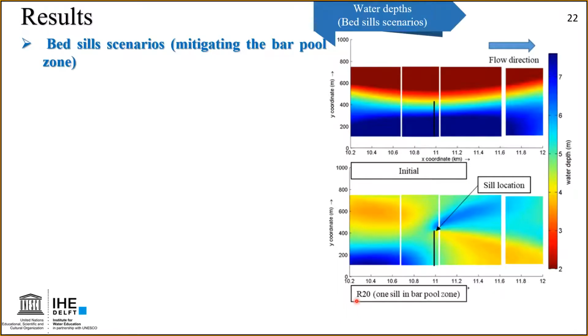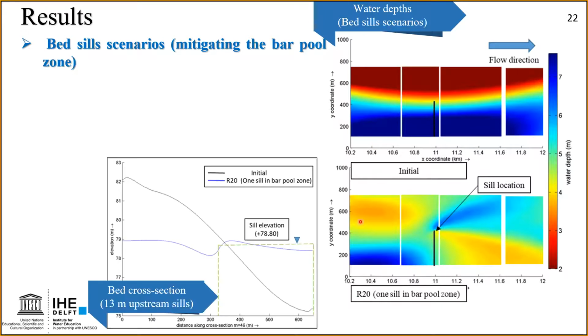We can see that the cell successfully redistributed the bed levels in its zone, as it could mitigate the hybrid bar here, and also make a filling process for the pool side, as it redistributed the flow, as we mentioned before, so a higher flow velocity here could mitigate this forced bar. And as you can see, the final cross section is more or less uniform around the undisturbed elevation we put for the cell.